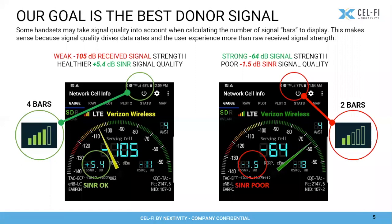Now this is kind of a clever way for, newer Samsung phones do this, iPhones do this. They take signal quality into account when they calculate the number of bars to display. So if you have a poor donor signal coming into your system, you can have all the power you want, but you still may only show a couple of bars on your phone, and that may not be a pleasing sight for your customers. So again, we're really going to concentrate a lot. Please keep signal to noise in your mind in the background, because that's really what we're trying to maximize here.